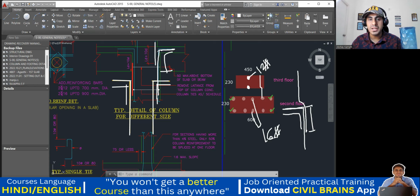And how much should be the lap length? They are mentioned: LD plus 10 times the diameter. So this should be LD plus 10 times the diameter. This much lap length you are supposed to provide here. Got it? Understood the concept? So this was all about these two clauses, and I've explained that through an example to you. Now come to the other case.